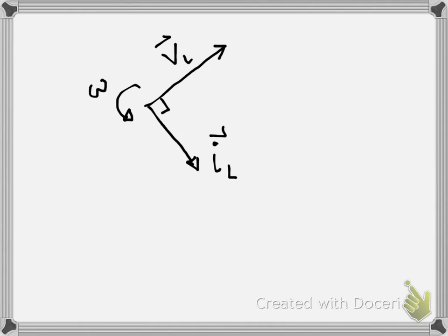So just to represent this with phasors, we have the voltage applied to the inductor. We're representing that as a vector pointing in some direction, and we know that the current lags the voltage by 90 degrees. So we can draw the current phasor as a vector making 90 degrees with VL, but behind it, since the direction in which these vectors are rotating is omega as indicated there, the current needs to be 90 degrees in the clockwise direction. That means the current lags the voltage for an inductor.